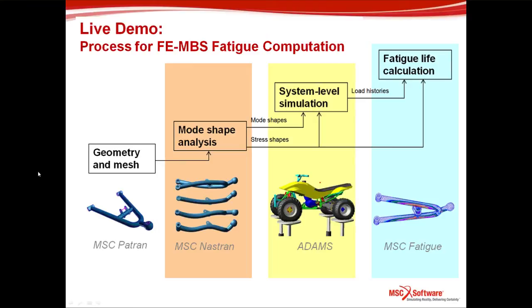And just allow me to rekindle a bit the previous session. The process that we're trying to follow is one of starting from finite element analysis, generating, of course, the component and the mode shapes of this component. The mode shapes are used because we want to provide a reduced stiffness model to Adams, and so that Adams can conveniently calculate the participation of each of these modes to the analysis, and then MSC Fatigue at the end of this loop can superimpose the modal participation to reobtain the stress history and perform very computationally intensive fatigue analysis at very low computational cost.